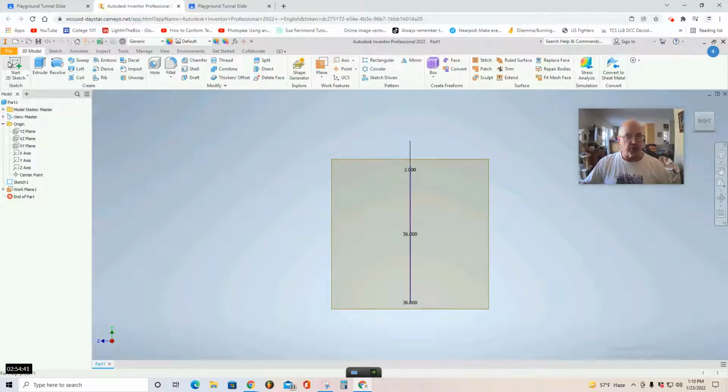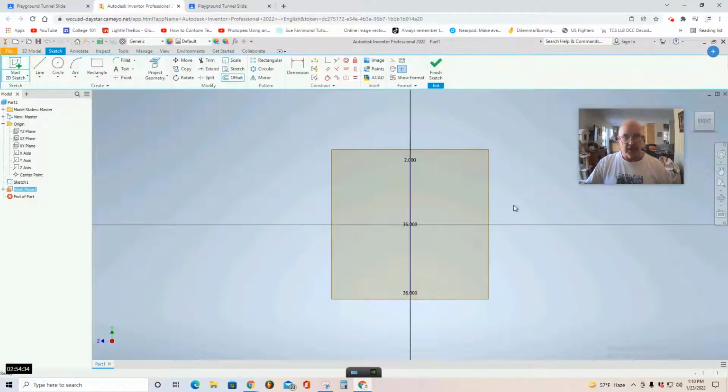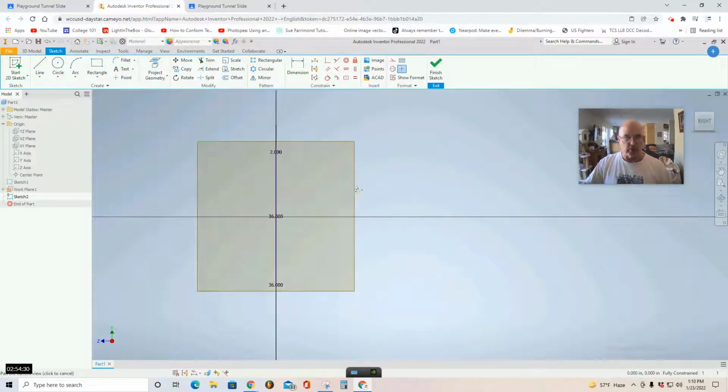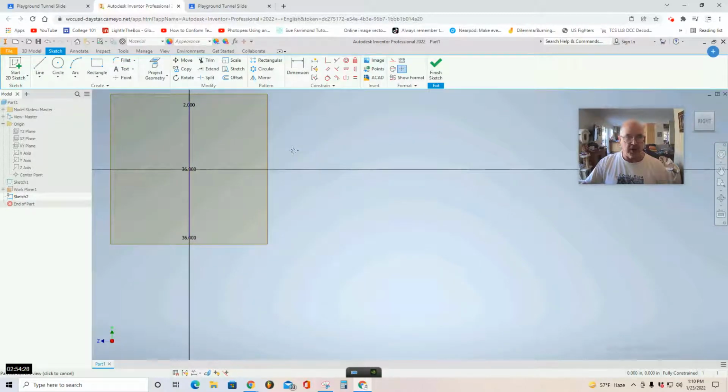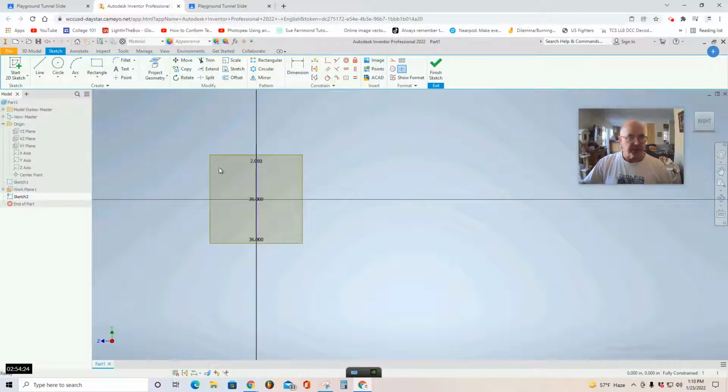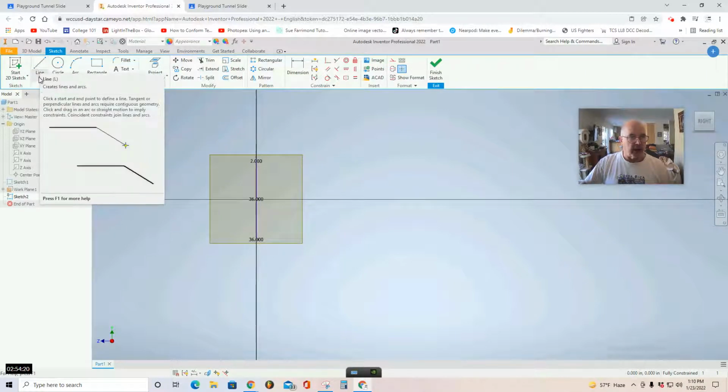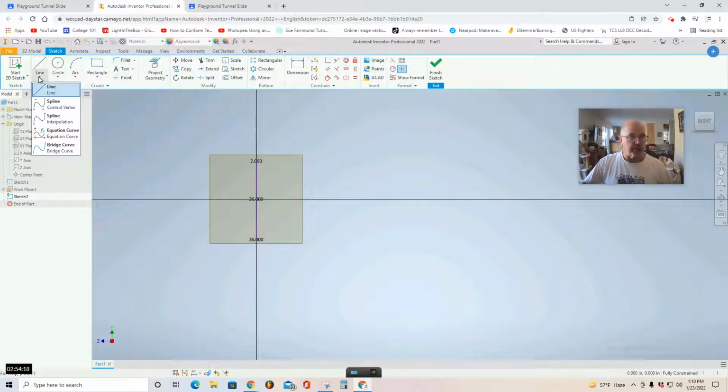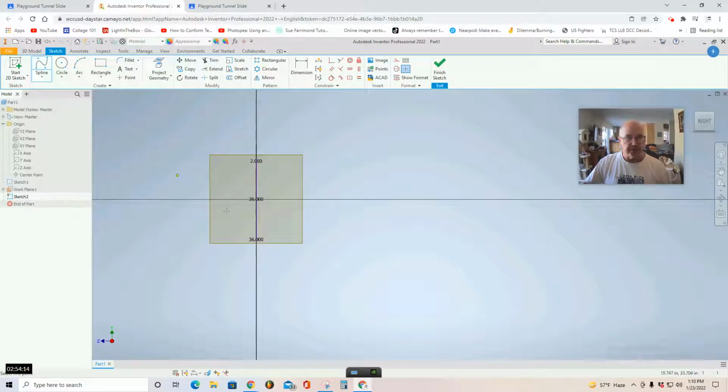to start a 2D sketch, and you'll click on the perimeter to activate. And I would press my pan tool, middle mouse wheel, and move it to the upper left. Zoom out 1 click. Now, here's the line tool, and under the line tool is a tool called the Spline tool, Control Vertex. So I'll select that option and select right at the origin.